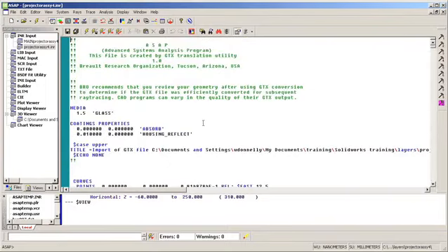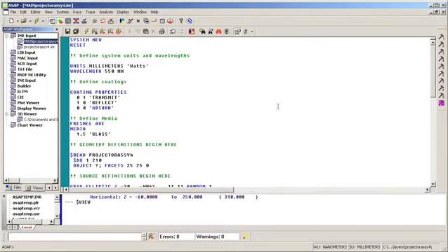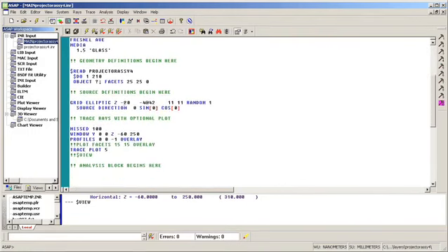So I can either confirm that geometry by doing a view facets command, or I can create a main file to call this geometry and read it, and then do other ASAP commands associated with tracing rays and any kind of analysis I want to do. So I've done this beforehand, and here is a basic setup for my main file. I called this main projector assembly 4. And this is where I call the INR that was just created, the geometry, read this projector assembly. I've created a source further down the line, and then some plotting and tracing.